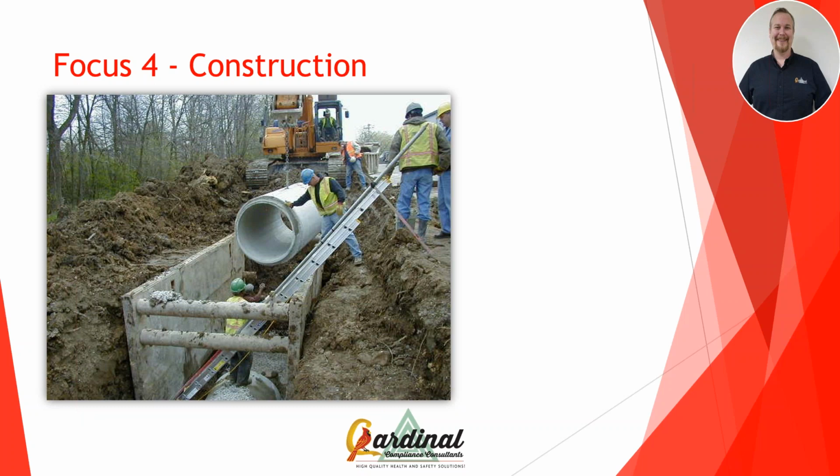So let me ask you, what happens if the hydraulic controls in that excavator fail? There's that possibility he could drop that load. Or what if one of the chain links fails in your lifting device? And if you've ever placed pipe like this, the connection point on that pipe is actually a piece of rebar that's inside of that, cast in place. What if that rebar fails? That is a fatality waiting to happen, same as the man falling. So right there, we have falls, we have struck by.